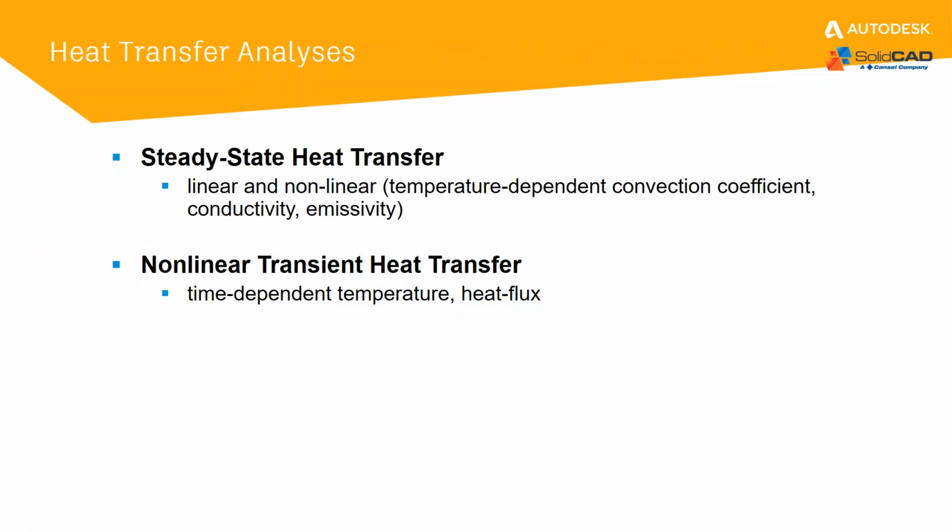So I mentioned heat transfer analysis, so we do cover steady state and transient, both linear and nonlinear. So temperature dependent convection coefficient, conductivity, emissivity, as well as on the nonlinear side, time dependent temperature and heat flux.